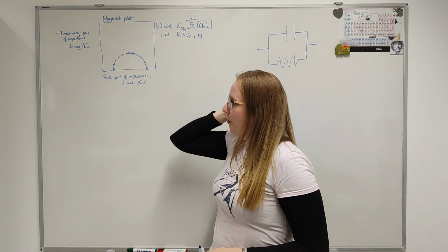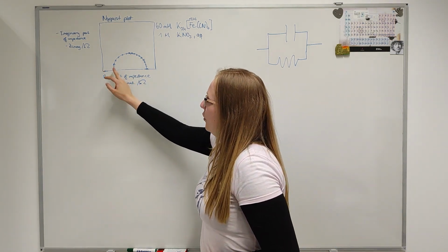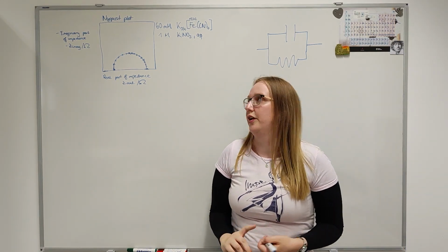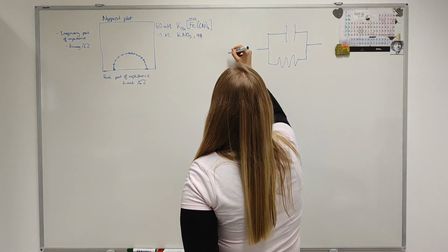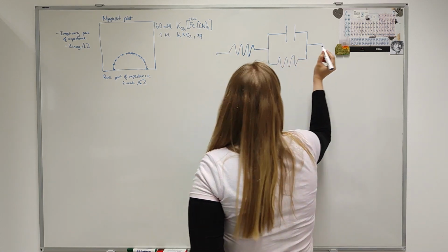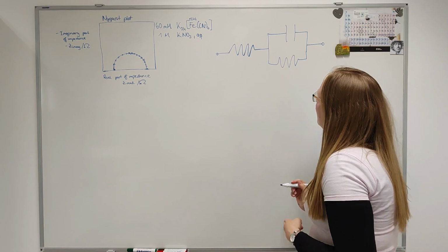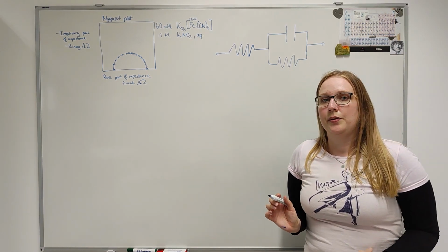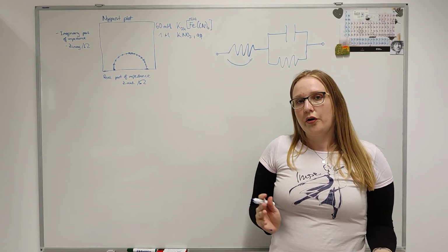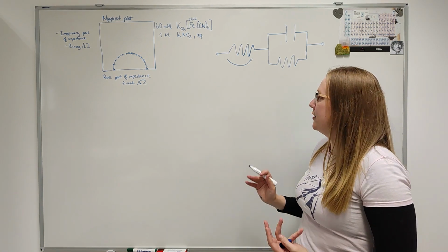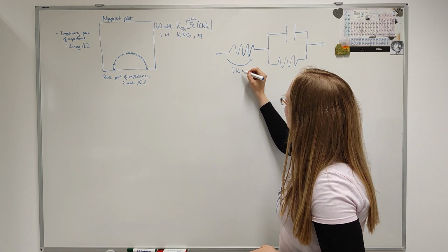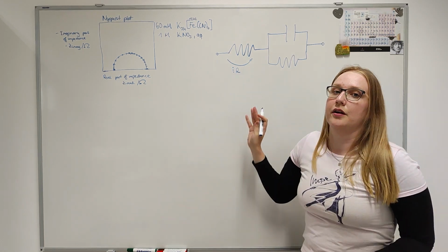That means for frequency independently, we always go through a certain resistance, and we need a resistor which accounts for that in our equivalent circuit picture. So let me draw another resistor here. If we try to make sense of that, we have to think of where this voltage drop we always observe comes from. All current we send through our electrochemical interface experiences this voltage drop. So we obviously have a resistance here. So what could it be?